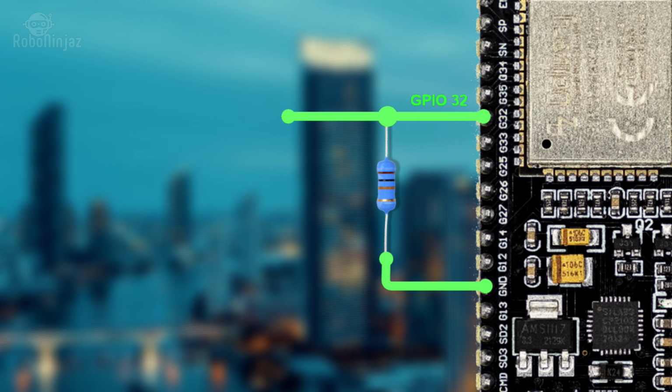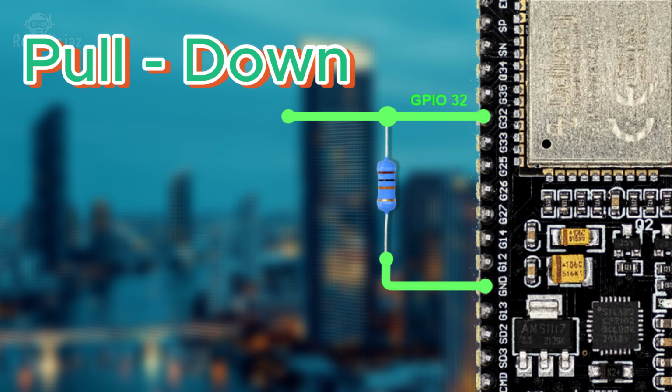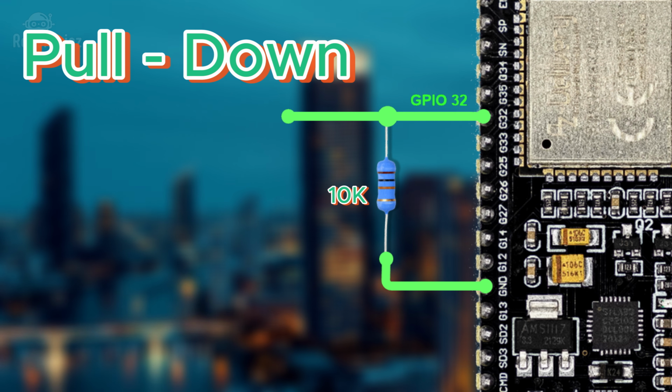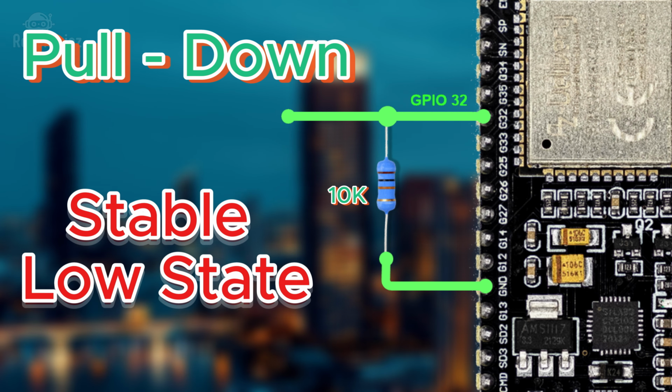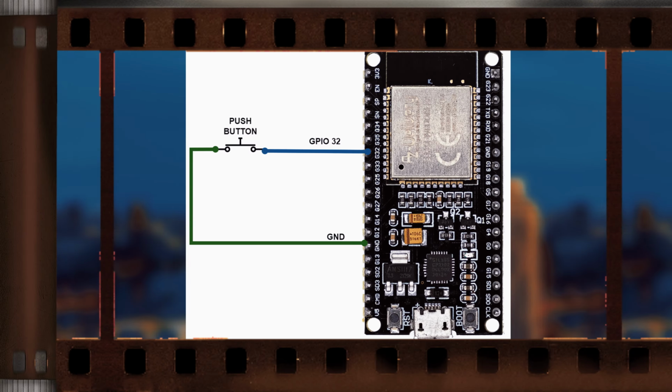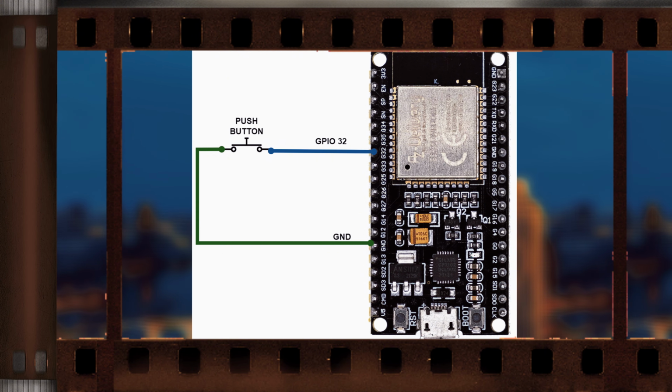Similarly, this is the pull-down configuration. In this setup, a 10K resistor is connected between the GPIO pin and ground or 0 volt. The pull-down resistor gently pulls the pin down to 0 volt, preventing it from floating and ensuring a stable low state. Alright, let's go back to our circuit.